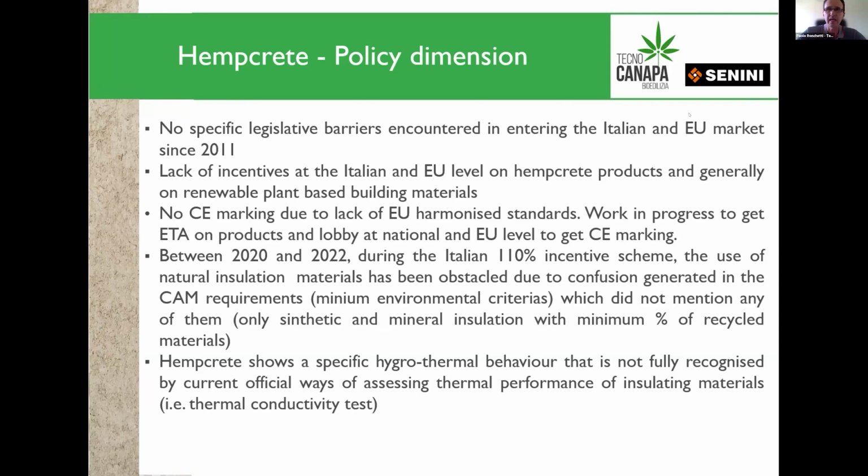However, hempcrete is a dynamic material which shows better performance than the other conventional materials, and that is not measured by this specific test. What does this mean? It means that we follow the conventional rules, so we apply specific thicknesses of hempcrete, but at the end of the day, the performance that we supply is much higher than the theoretical one.